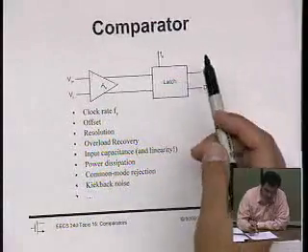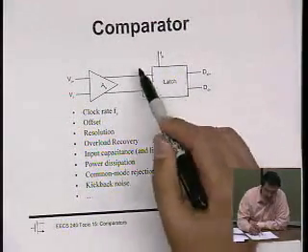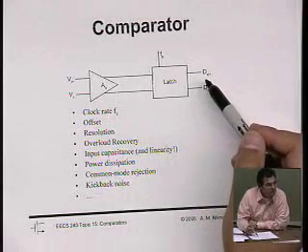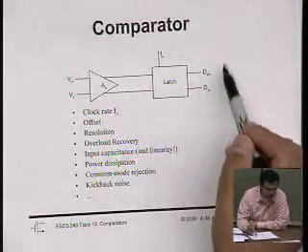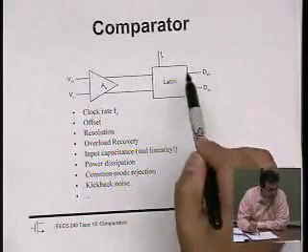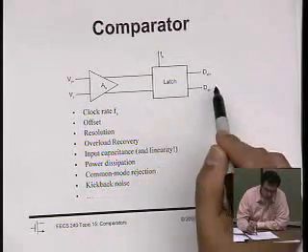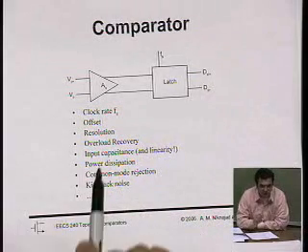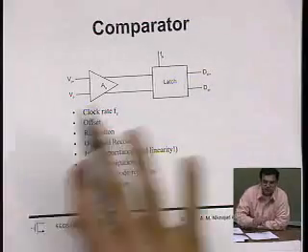And then finally, the nice thing about a latch is that I can design it so that on the falling edge of the clock, it clamps the value and it doesn't change anymore. If I always had the input connected to this digital level, it could change a lot. Just little noise spikes could produce bounces in the output, which could wreak havoc with our digital circuit. So for a digital circuit, we need a decision, and even if the decision is wrong, we need it to be consistent for the clock cycle, for everything else to work.